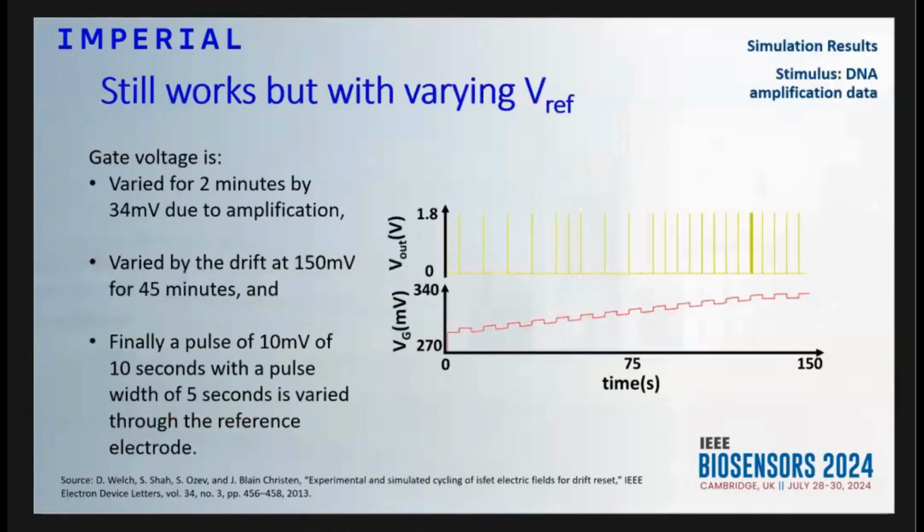And so I go back to literature and I start delving around and I find something interesting. People have sort of tried to stimulate cycling through the reference electrode to get rid of drift at a certain angle. I did not want to use a big capacitance. You can just increase the size of the capacitance and you can slow everything down.